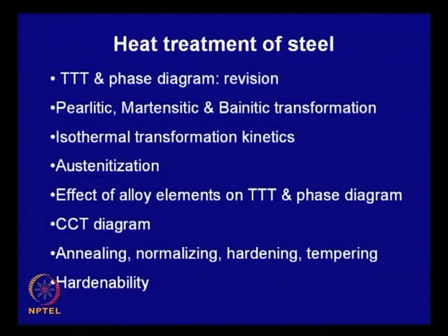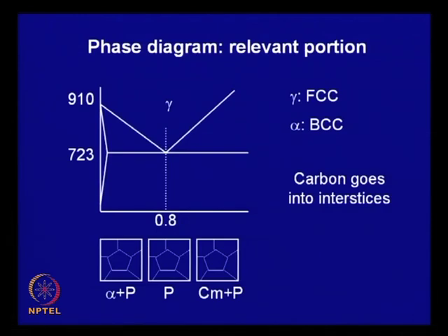When you heat it to austenite temperature, that cementite or carbide dissolves in the matrix, you have a single phase structure, and when you quench, you retain a high amount of carbon, no doubt. But we will see in this case, unlike precipitation hardening, instead of strength going down, strength goes up substantially, and we will try and see why this happens.